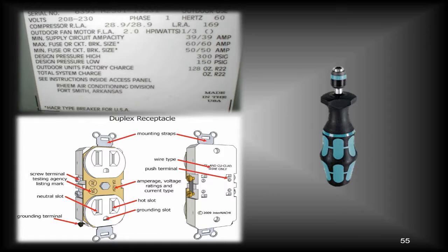That's telling you that even though you might have a breaker on the other end, you have to have a fuse, even though it's going to be redundant, in that circuit. So those things are really key to hone in on and understand what the manufacturers actually wanted. This particular one says fuse or breaker.